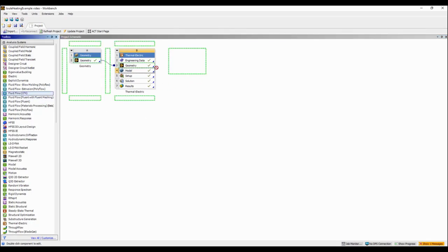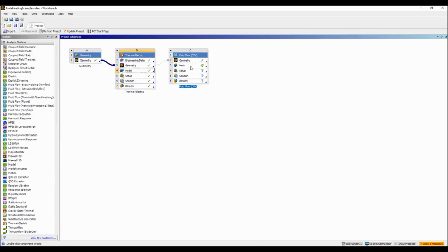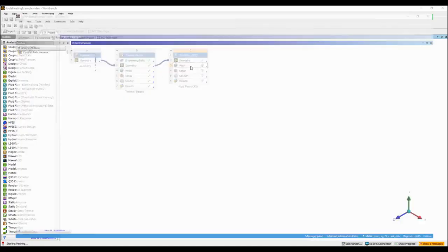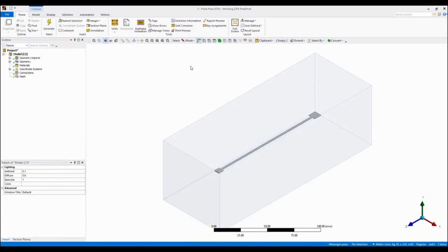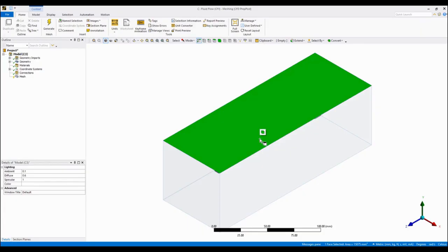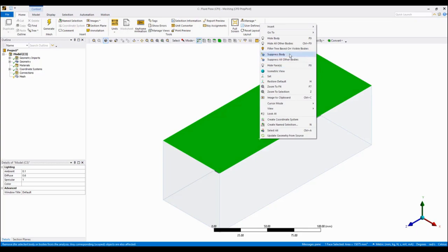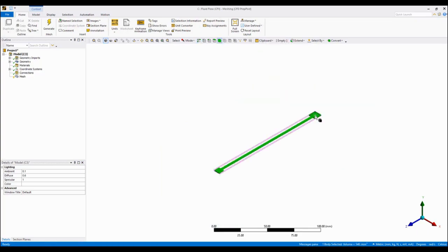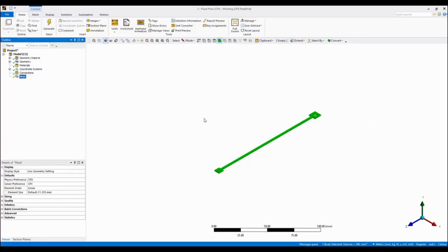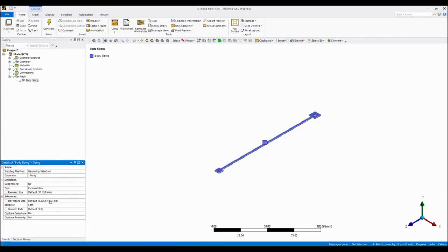So let's do a CFD analysis now. I'm going to use CFX. It has pretty easy to use thermoelectric analysis capabilities, and here we can put in the air box, so we can actually blow air across our conductor. Same interface for meshing. One of the things I want to do is set the mesh to be the same on the conductor itself. So highlight meshing, we're going to put sizing in, and we're going to set a size of 0.5.